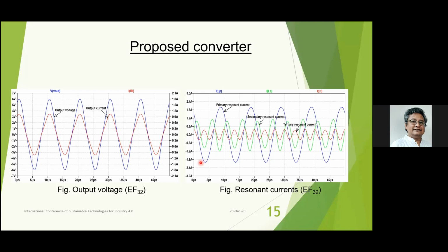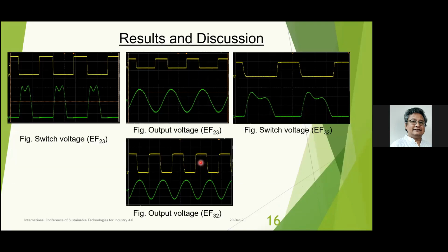Okay, thank you for your presentation. My question is, what is the output frequency you are talking about? I think it's in the megahertz or kilohertz range, isn't it? No, sir. Actually, yes, I got the point. Basically, this class A inverter is used for an amplifier, or we use it for an inverter. Here we are applying it as an inverter. The output frequency is similar to the resonant frequency of the converter, so that's 200 kilohertz.